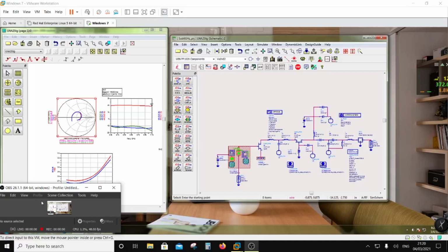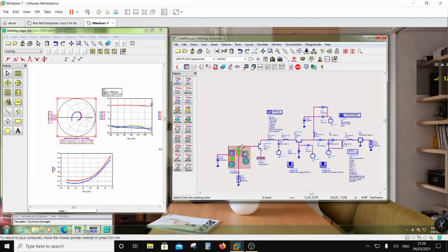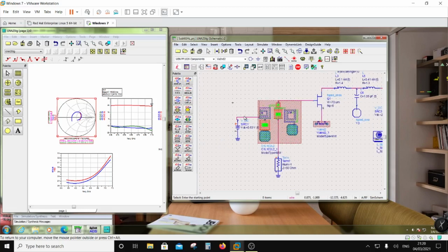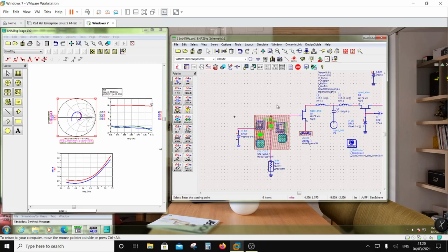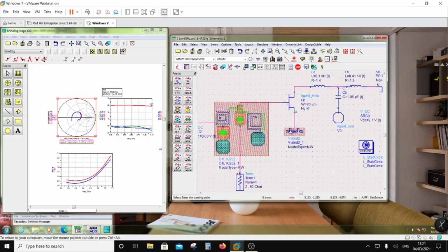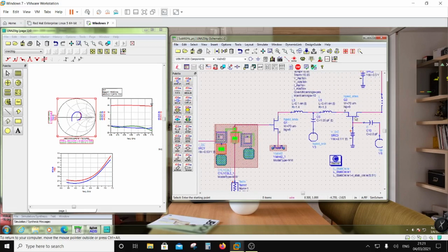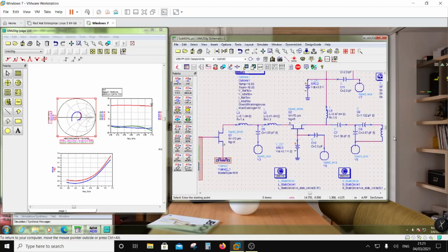Okay, so once I'm done with the simulation of the input stage, which is over here as a lookalike. So I have done a lookalike component which represents the layout, and this is my input port. This is where I put in the DC supply, and this is my transistor, right? So I have transformed the input side of this transistor into a layout. Okay, and then I have also refined according to the layout. I have also refined the VI inductance for this transistor, and after that I have tweaked these components to get the performance as it was.